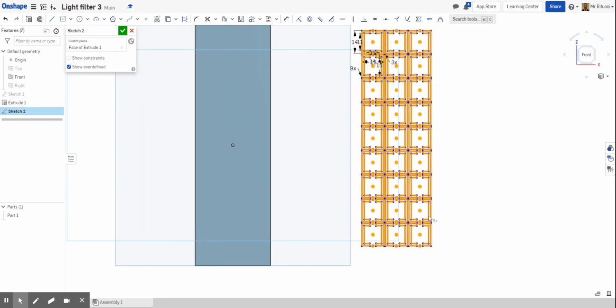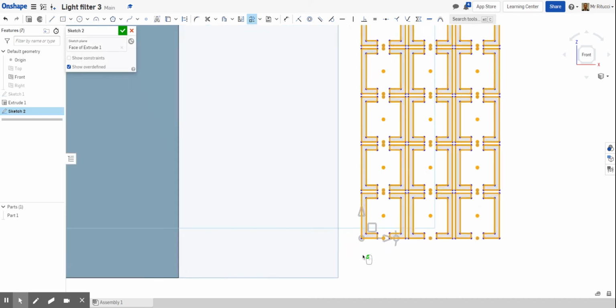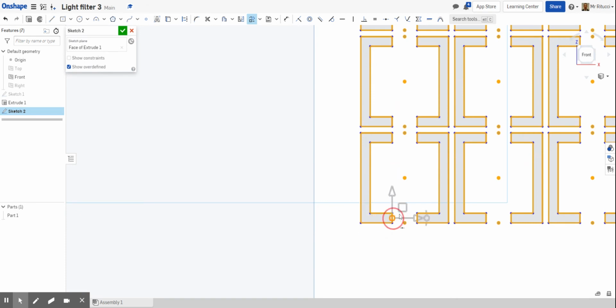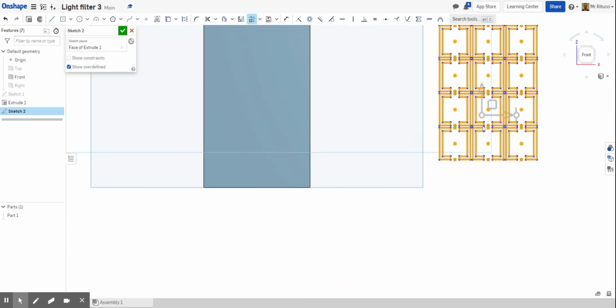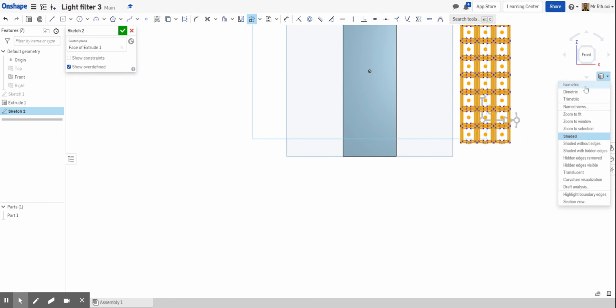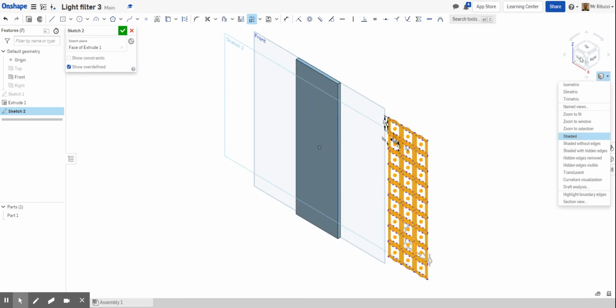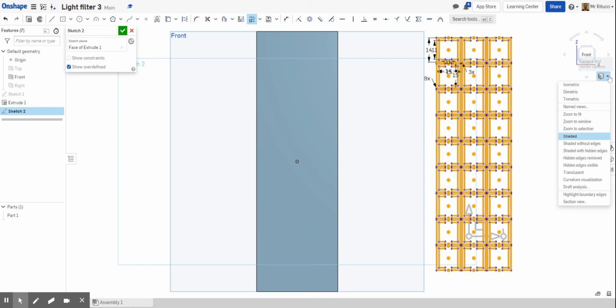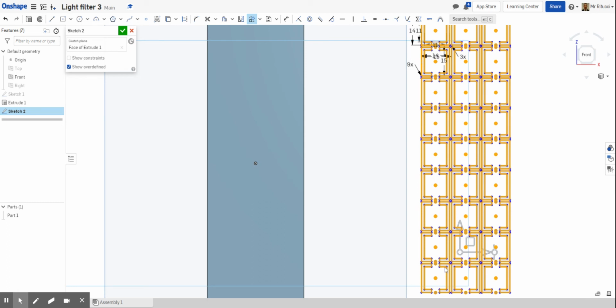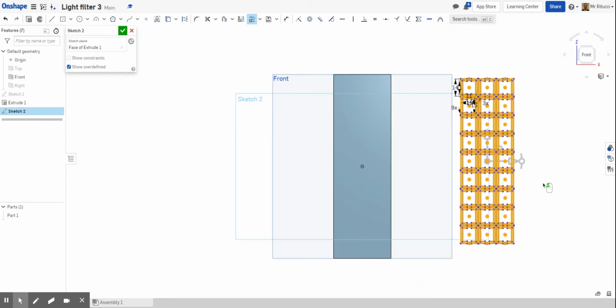Okay, and right click again and go to transform sketch entities. This time don't click the arrow, click the little circle. So zoom in, click this little circle, and that allows me to move this to the center of my drawing. If it was in this corner down here, that's where it's taken the center from. So I want the center to be from the center of my drawing, which is like here, like that.